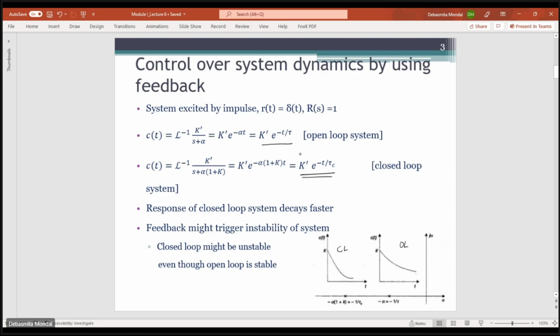We have talked about how using this feedback mechanism, we can nullify or eliminate the effects of noise and disturbances which might be there in the system. So now let us consider an open loop transfer function which looks like this, and there is some noise or disturbance signal coming in at this point, before the transfer function GB. This is unwanted noise, so we will see what its effect is on the output.